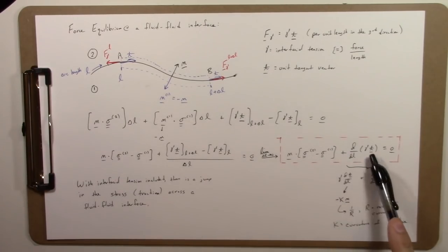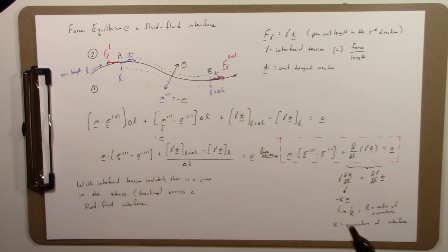So basically, we've decomposed this derivative into two components. And so we say the difference in the stress across an interface is equal to the sum of two terms. One is the interfacial tension multiplied by the curvature multiplied by the normal vector, so that acts in a normal direction. We have a part here which is due to the variation of the interfacial tension along the interface multiplied by the unit tangent vector. So there are two different effects. A curved interface can influence this stress balance even if the interfacial tension is constant, whereas a planar interface, there will be no curvature, so this term goes away, but if the interfacial tension varies along the interface, even if the interface is flat, there can still be an effect in the tangential direction.